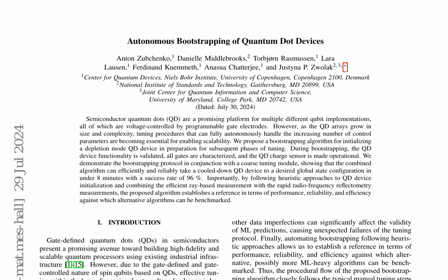The bootstrapping process starts after cooling the device down to a few mK and involves determining the operational ranges, determining charging energies for each quantum dot, QD, and making the local charge sensing system operational.